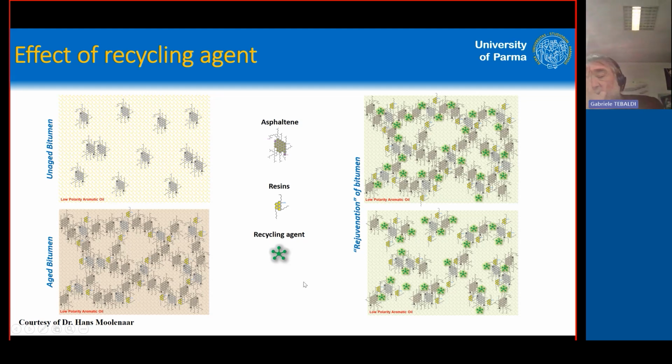We have to remember very clearly that we call it rejuvenation, but there is no rejuvenation. The aged bitumen is still an aged bitumen. What we can do is attack the bad part of the aging and mitigate its effects. But we always have an aged bitumen in the end. This is something that I think is extremely important to remember.